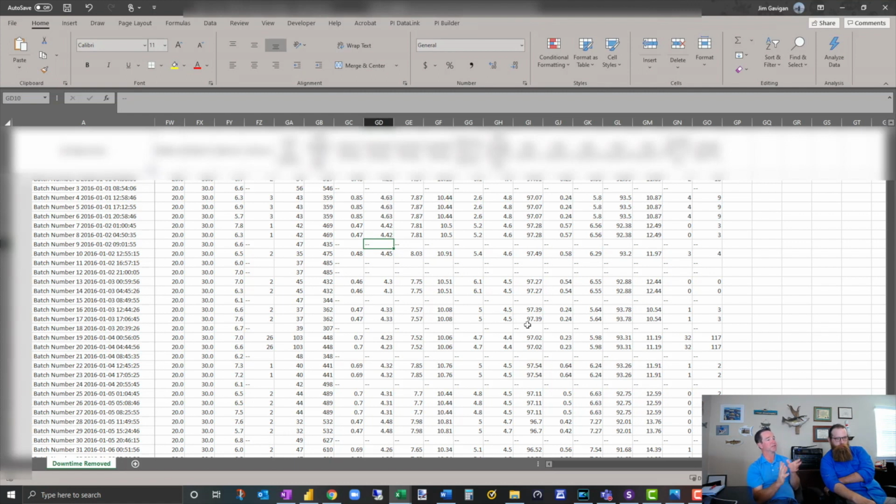And the thing that's very interesting about SIMCA, my friend that introduced me to this, he actually works at one of our customers. He said you can actually do a data set merge in SIMCA. He did this in Excel with a macro where he was lining up the data. But if you have lab data that has one set of timestamps and then all this batch data that has a different set of timestamps, it'll actually do the fill down based on those two timestamps. It'll actually merge that for you. Wow. There's actually a data merge capability in SIMCA, which is huge. Here I didn't really have that choice, because he already had it here.